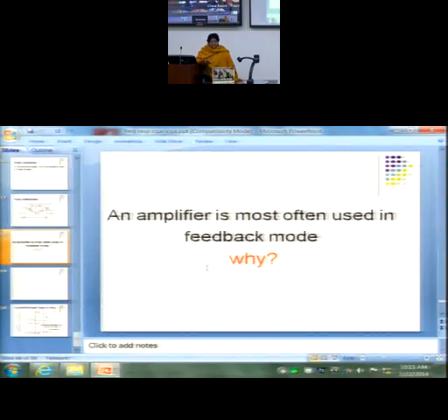But I can extend its definition. So it gives me more reliability of the gain. The effect of fluctuations on the circuitry reduces to nil. Always remember this concept. That is why negative feedback is a very important concept in design. I think you all must have read it in your control systems.